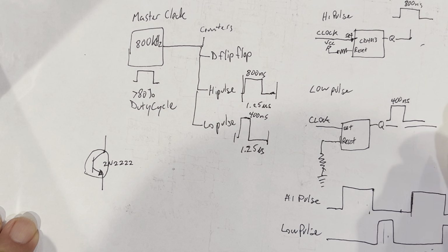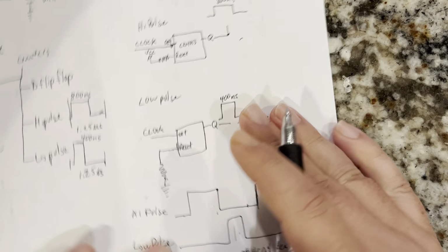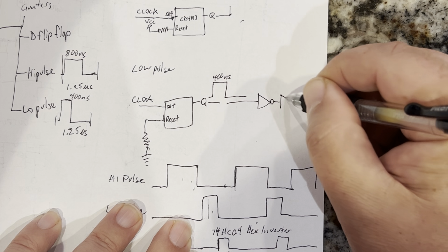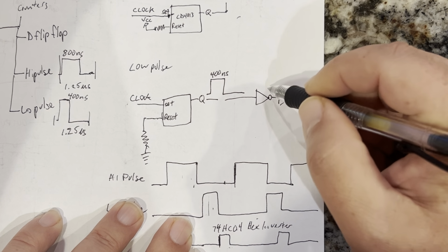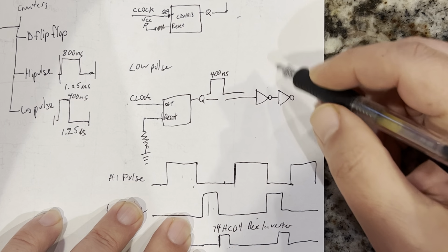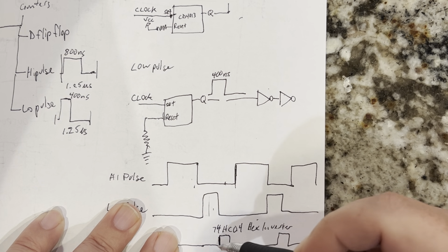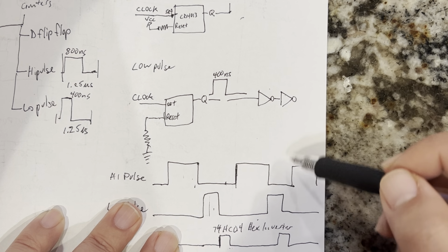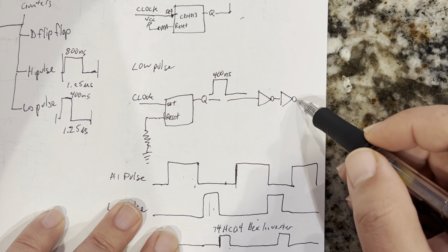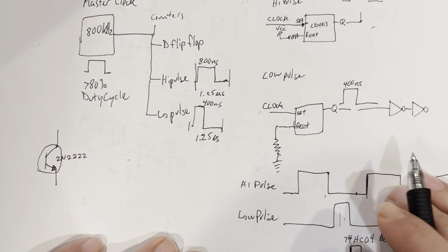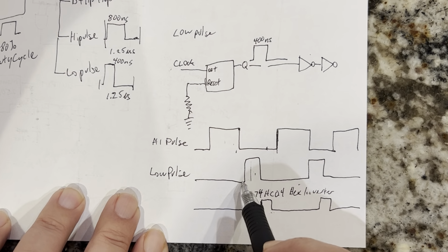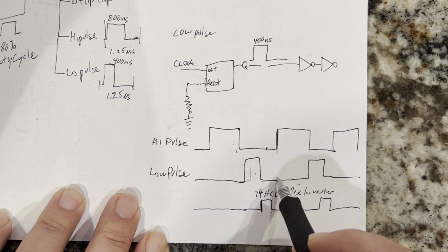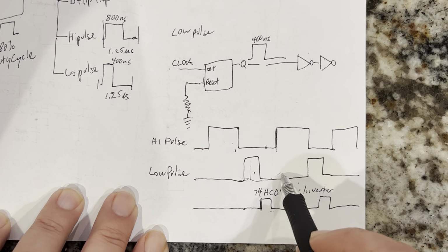And when you take the low pulse signal and you invert it using transistor inverters 2 times, one time it inverts upside down, and the second time it inverts right side up. And at the end of that, I got a 600 nanosecond delay from these transistors, which was equivalent to the amount of delay that I needed to make.